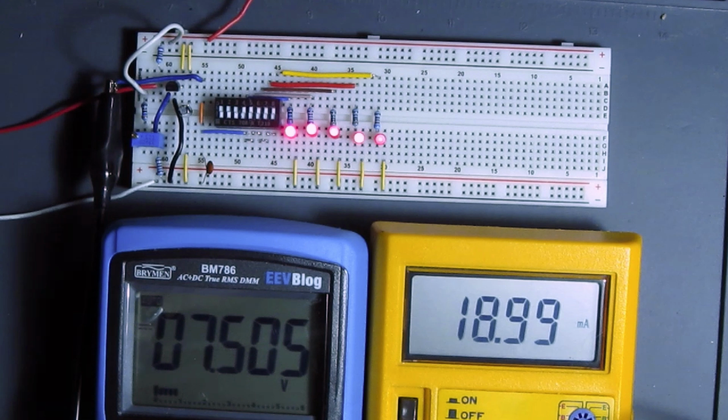I'll take it. For a production circuit, I'd have to analyze things like manufacturing variability and thermal stability, but this is good enough for a one-of-a-kind. We've seen here how we can use a bandgap reference to get quite a precise voltage source, good enough for stable musical tuning. Trying to do that with Zener diodes would be a fool's errand.